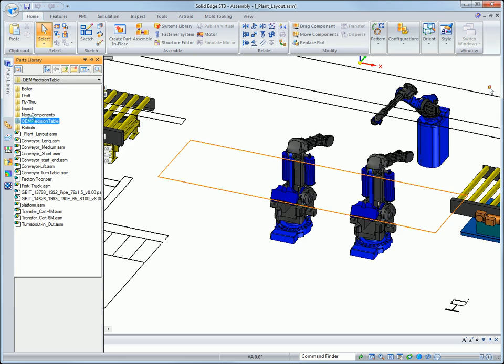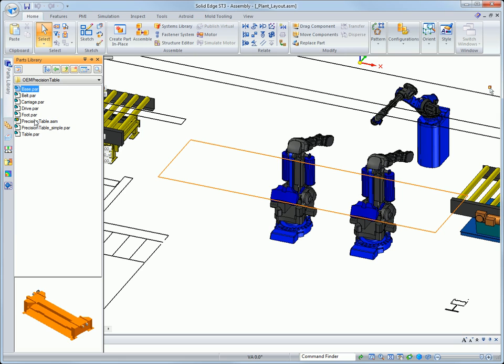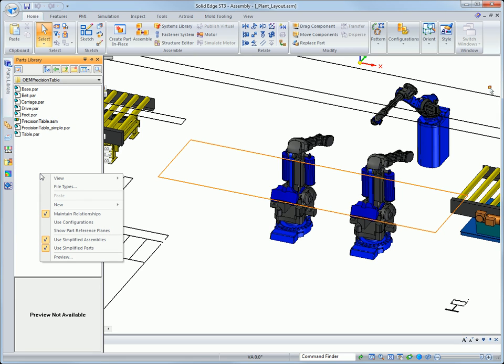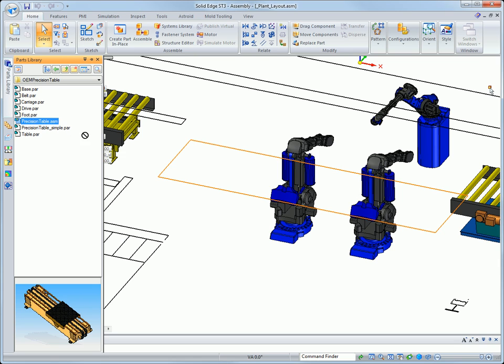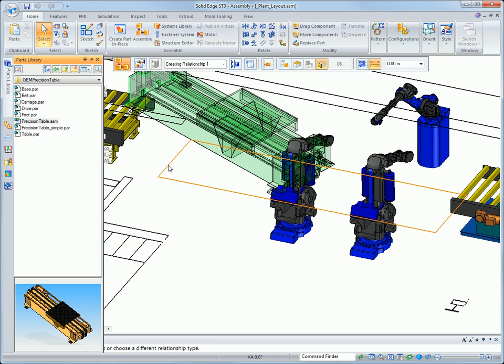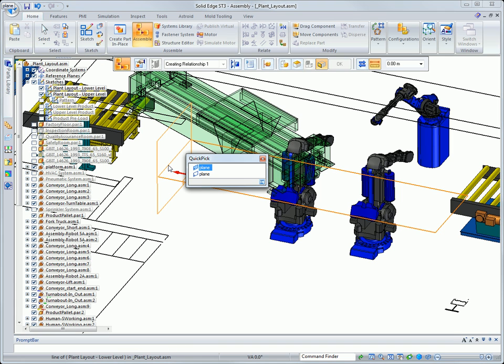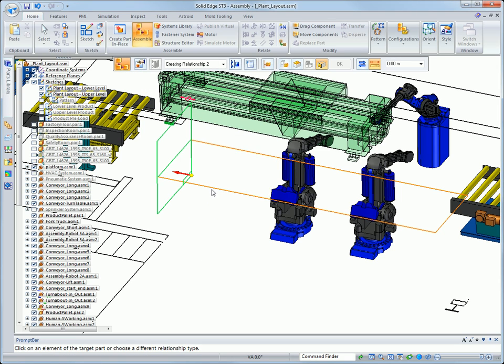In this next step, we'll drag in an OEM part into the assembly and position it relative to the assembly sketch. As part of our process, any OEM data received should contain a simplified representation of the part or assembly. This process is quite simple but yields some drastic performance increases. Remember that squeezing every drop of performance from our system is important when dealing with massive assembly designs.